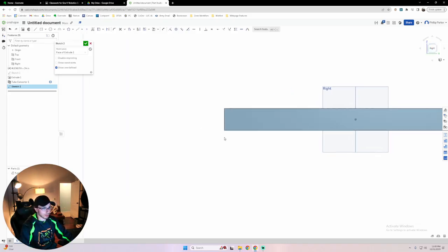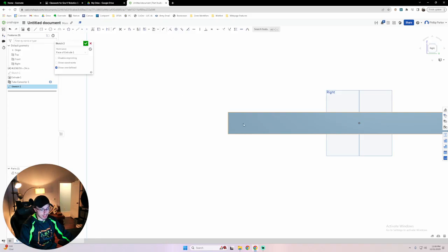Now what I'm going to do is I'm going to sketch off of this axis. I'm going to use a corner triangle, the G button. And I'm going to select here. I'm just going to drag it. I've constrained this corner to the corner of the tube, right?